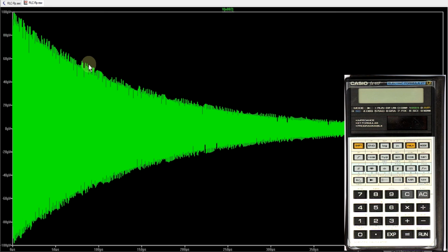If we would do this, we would count 100 cycles, and this number has to be multiplied by 5, and this gives the Q factor. Now 100 cycles times 5 gives 500, and so we get exactly the same Q factor by this measurement method.